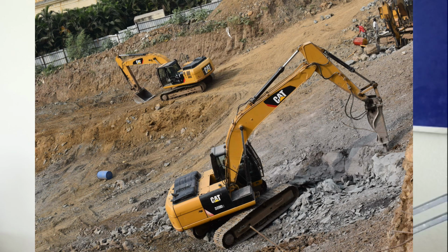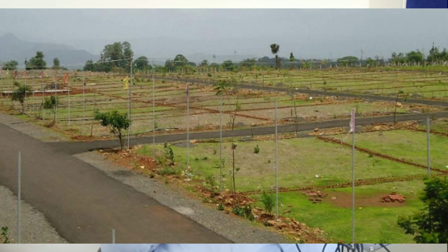The second method is by making use of a drilling machine and chipping machine. You chip it, make it small pieces of rock, and remove it. So these are the two methods. The first method is the cheapest. The second will take some time, and the cost is also much higher compared to the first method. The first method is only applicable where you won't find any existing building surrounding the site.